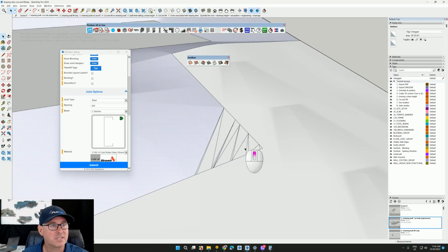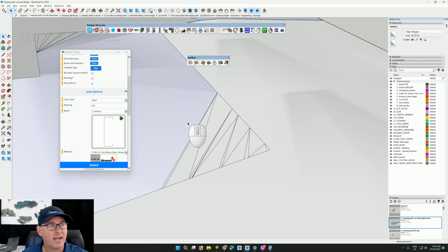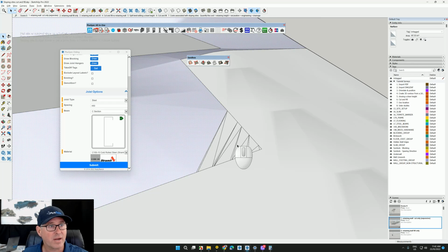If you ever come across this instance where, when I intersected or stamped the house, it created a whole heap of lines there for me, I'm going to use the eraser tool. You'll notice down the bottom here, I'll close that for a second, it actually tells me what to do. If I push Control, it will soften and smooth. So Control and then rub it.